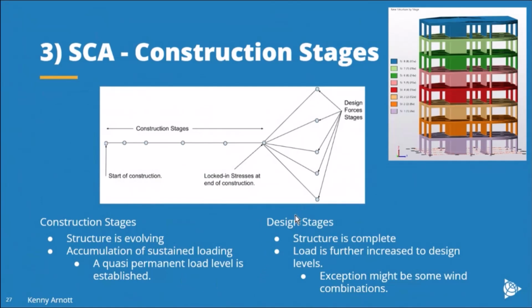And then we move on to design stages. So that's something further down the road where we're actually looking at ultimate load levels for design forces or also service load levels. So we've got a series of design forces stages. And as I'll come on to later, we have 5 of those, and all of the load combinations that you would normally define get assigned to one of these design forces stages. So that's really the topic of the next webinar. I'm just trying to make you aware of this general principle that we've got the construction stages, and then we go on into the design stages.